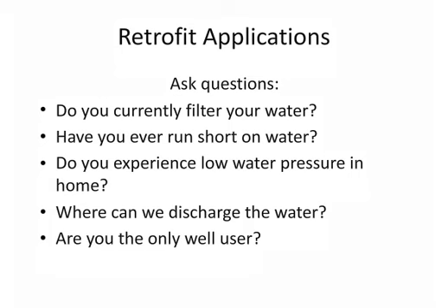Mr. and Mrs. Homeowner, where can we discharge that water to? Where did you have in mind? Remember, when this unit runs, we need 2 gallons per minute per ton. And kind of give them a general idea what they're looking at. Sometimes people have a pond or a creek. You want to make sure that is allowable under the municipal regulation. Where are we going to put it?